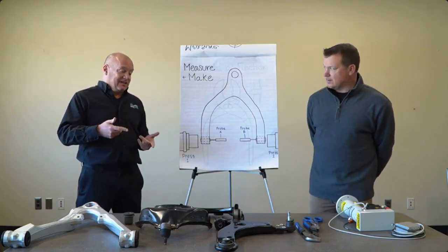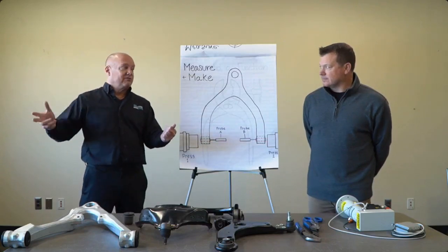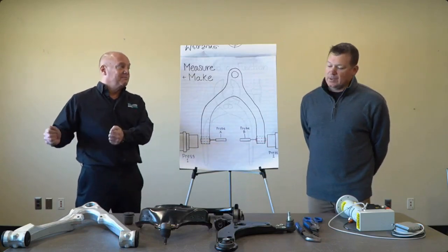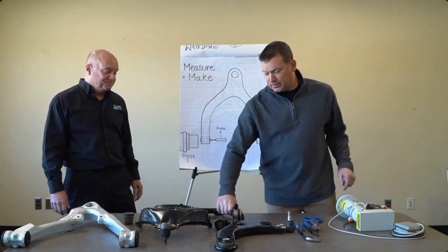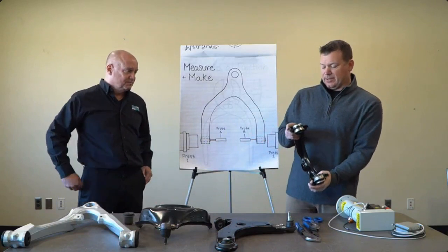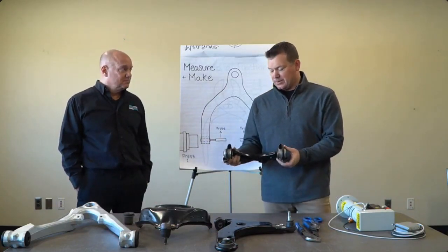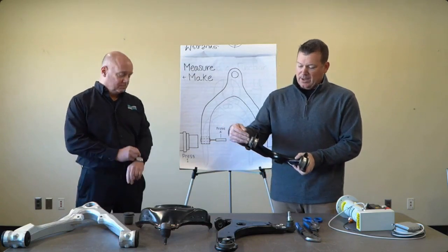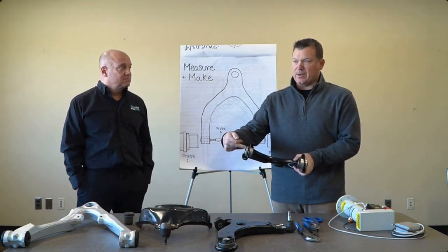One of the other key things is that however you're measuring in station, if you have an offline gauge, you have to measure it the same way. Right. Otherwise you get correlation problems. One of the neat features of some of our techniques is we're not measuring while it's under load, because remember this is being pressed in with a high amount of force.